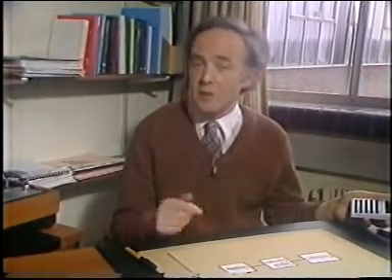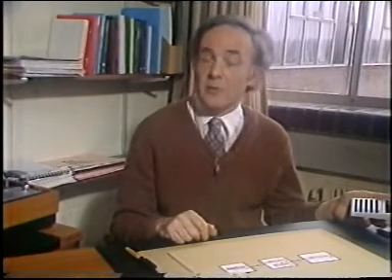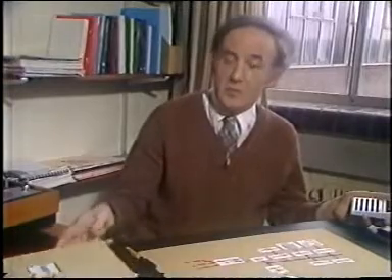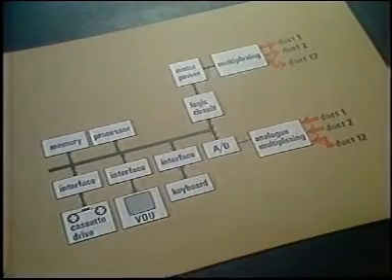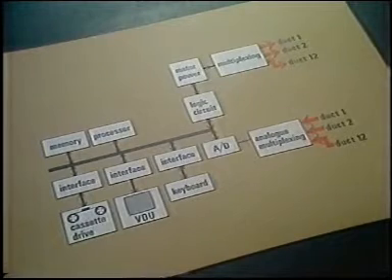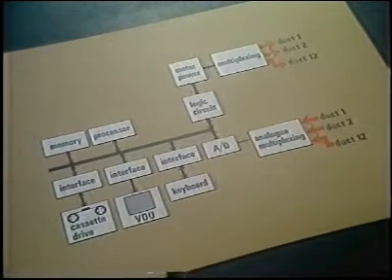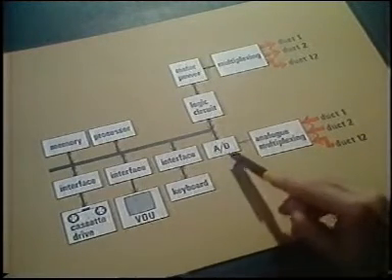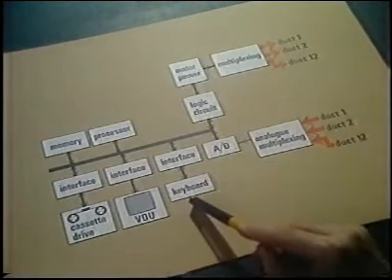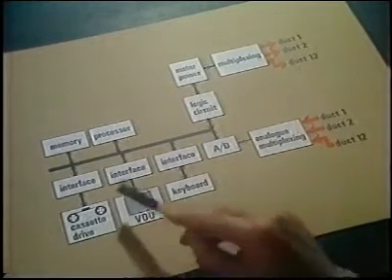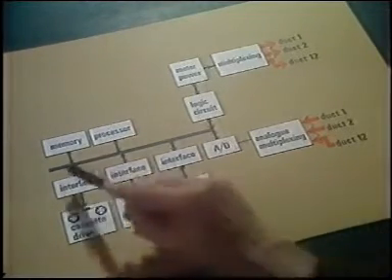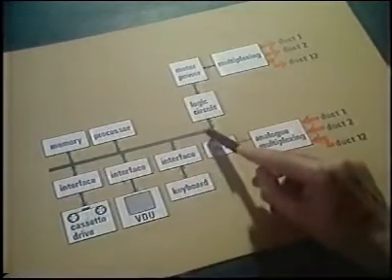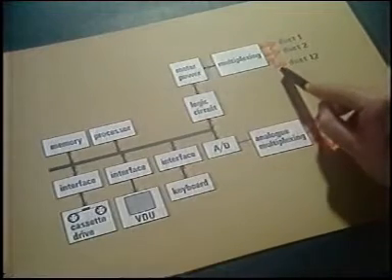But more generally, we might expect to find some combination of analog and digital techniques, as we talked about in units 12, 13, and 14, and in the 9th television program, which went along with those units. Remember there the printing press, which we talked about, and here is the system diagram you saw in that program. It looks fairly complicated at first sight, but if we look carefully, we can see the various sections. For example, there are analog inputs here derived from the inking ducts, analog to digital conversion, and digital inputs from a keyboard and from a cassette drive and a display system, all combine various interfaces to a digital bus, a digital memory, processors and so on, which provide information to the logic circuits which drive the inking keys.